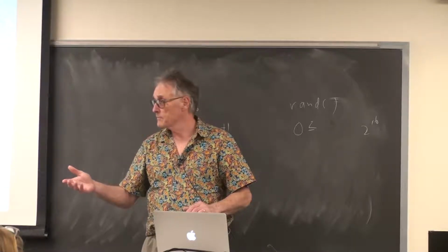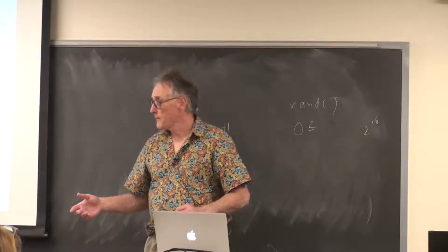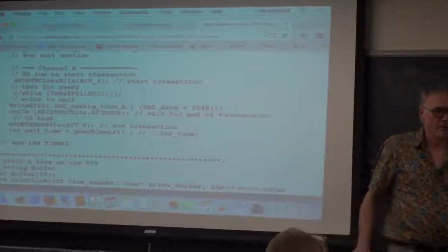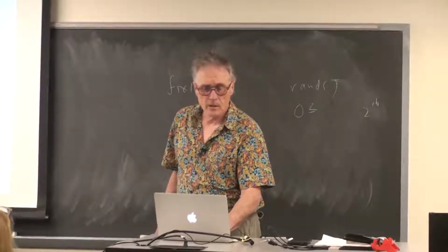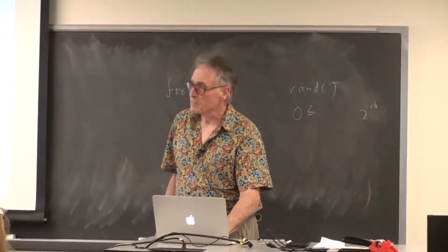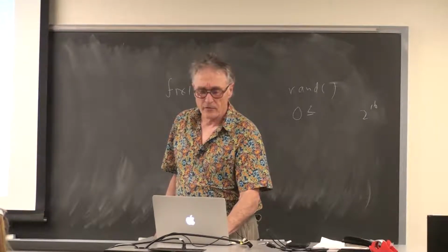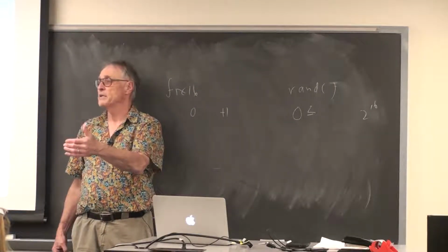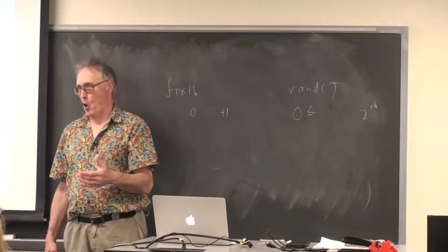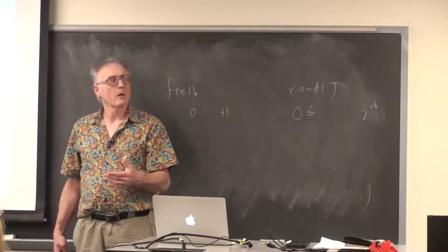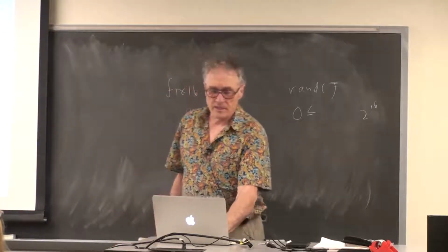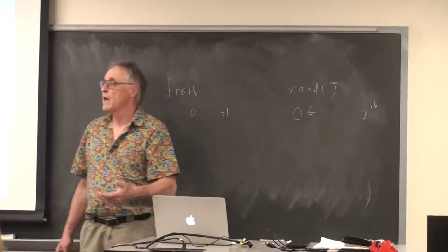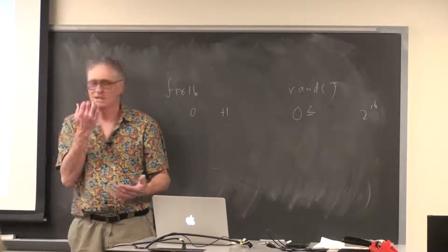I was just going to say that I did do a floating point while in my ISR and it worked last lap. You were running at 100 kilohertz or slower? 100 kilohertz. At 100 kilohertz, you can make the deadline because you have 400 cycles. If you do 2 multiplies, you come in at 367 cycles, you still make the deadline and the system still operates. The keypad just gets really slow. Did you notice that? No. Amazing. Okay. If you stay at 269 cycles, then you're using about half of the CPU for the interrupt service routine, and you probably couldn't notice that. Yeah, that was what we were doing. Okay.